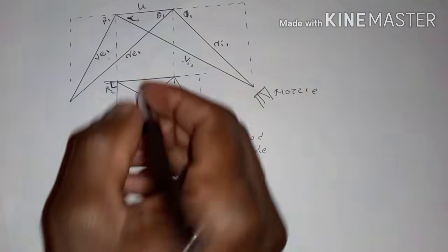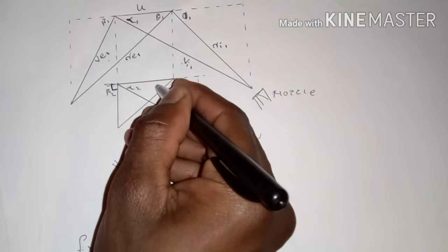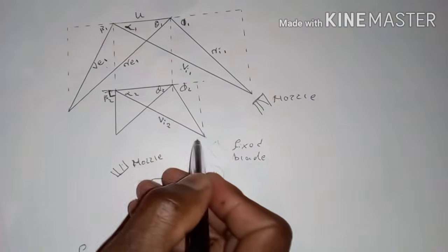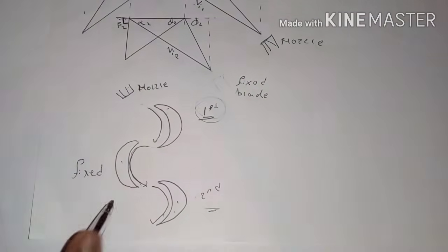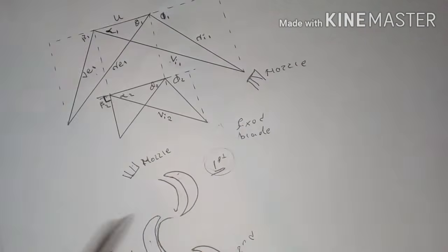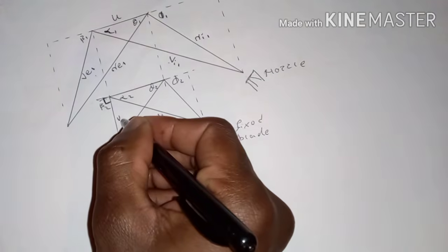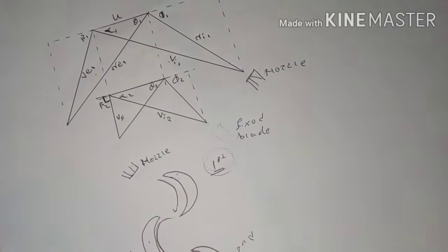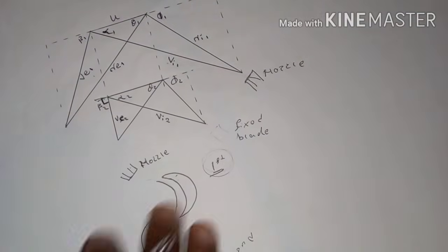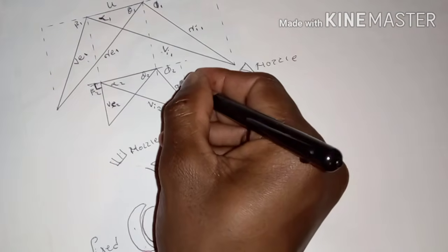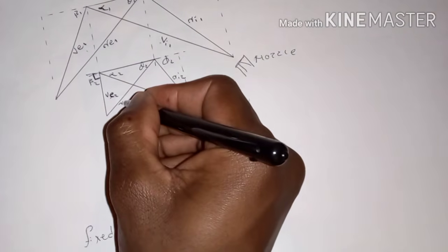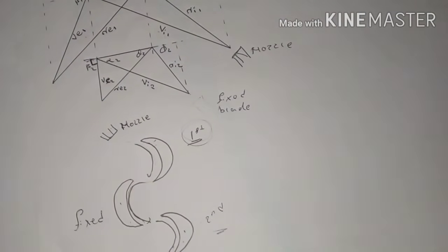So we have to represent it by saying this is alpha 2, this is theta 2, this is phi 2. This is the inlet velocity, the velocity at which the steam is leaving the fixed blade entering the second row, and then the velocity at which the steam is leaving the second row, not final, it's exit. And then relative velocity number 2 initial, then the relative velocity at the exit, also number 2.